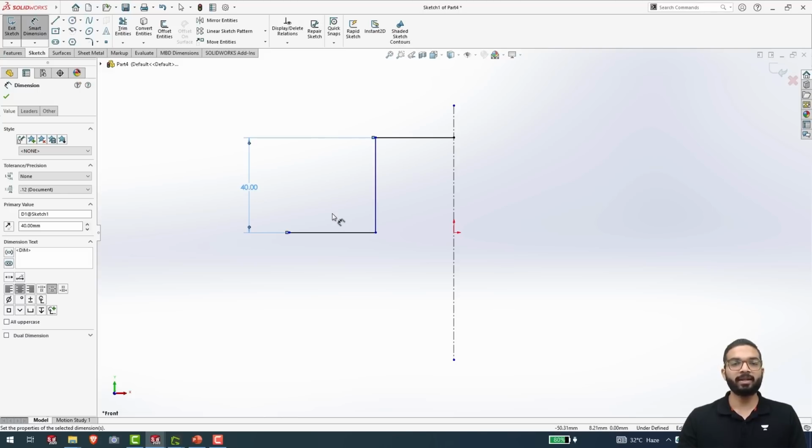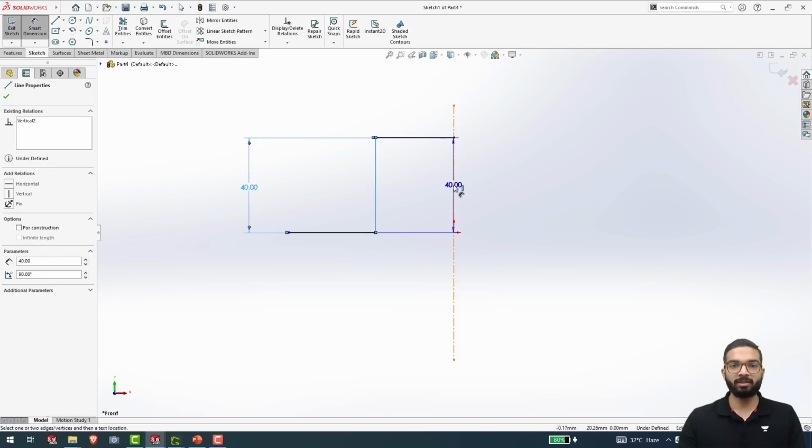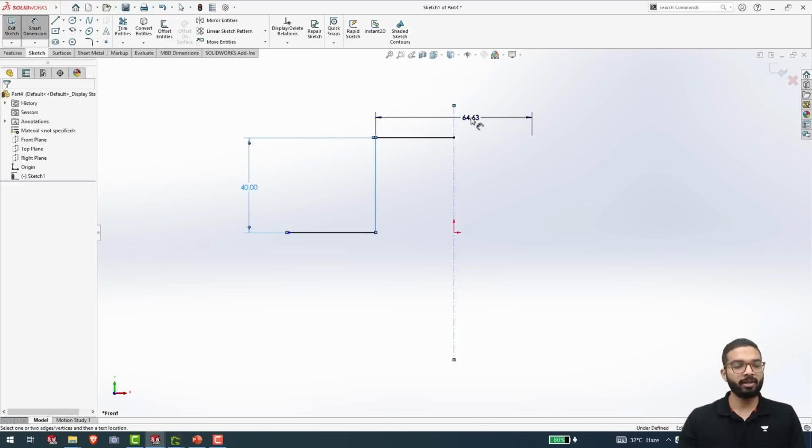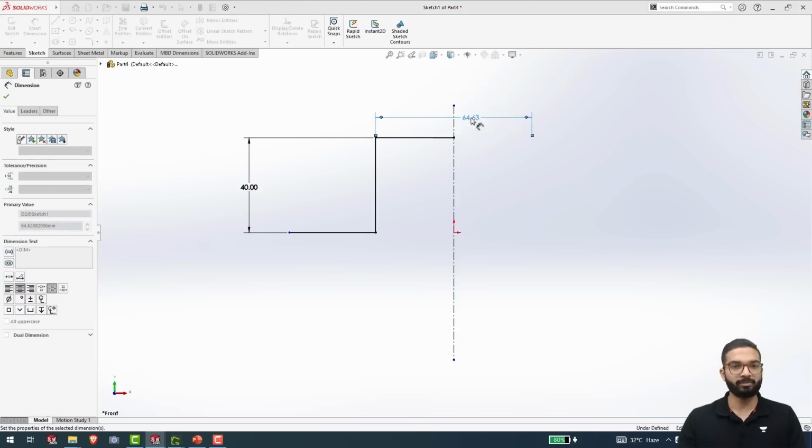In this case, if I extrude or create the thickness on either side, I will have to specify the length of this line over here as 1 millimeter less. I will show you why with the preview that will be shown while we create the base flange. Next, I will specify this with a diametrical dimension. This is 95 millimeters.